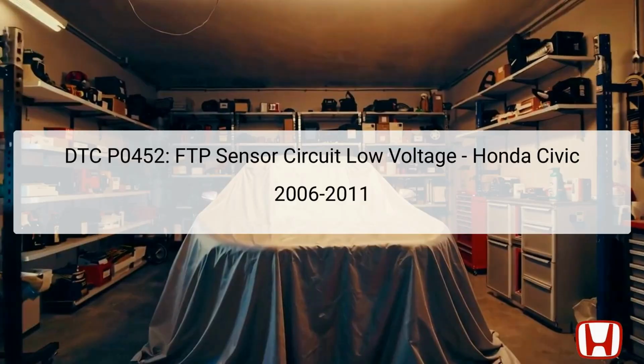The diagnostic trouble code DTC P0452 refers to a low voltage issue in the fuel tank pressure (FTP) sensor circuit. This occurs in the Honda Civic models from 2006 to 2011. The FTP sensor plays a vital role in monitoring the pressure inside the fuel tank and ensuring the evaporative emissions control system operates properly. Its location is typically near the fuel tank, making it essential for fuel system diagnostics.